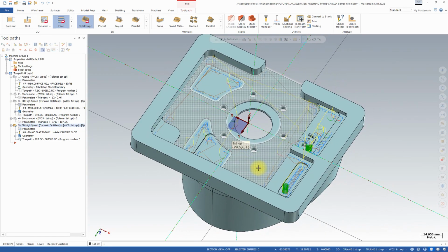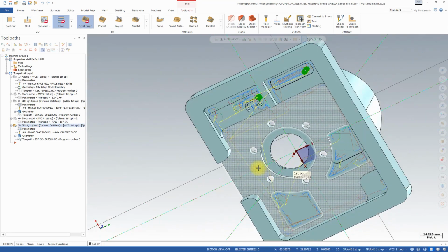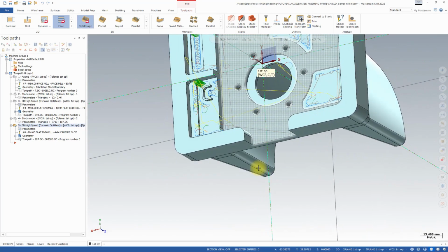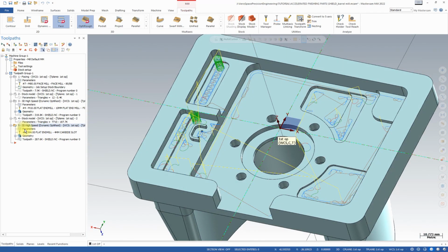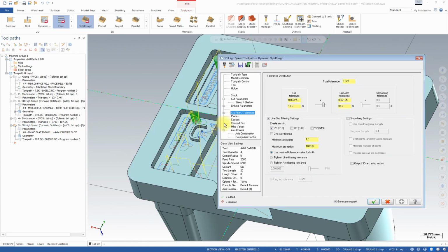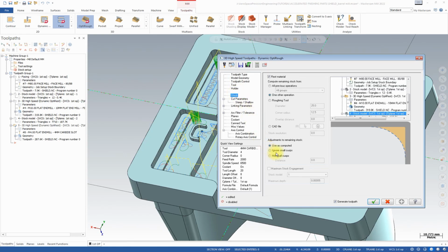And if you want to ignore the small cuts, you have to use this tool with check if we can eliminate the corner radius. That is minimum of the size of this cusp. Parameters. So in our case, our tool would have to be minimum of, let's say, 0.05, because this is the size of the cusp I want to avoid. And I want to ignore small cusps that are distance of 0.05 millimeter.